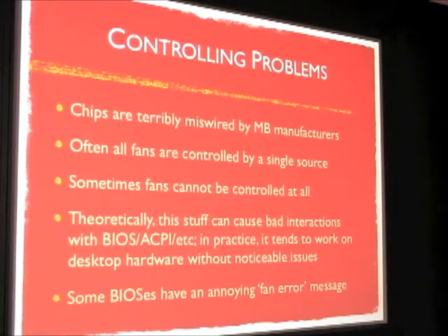And sometimes fans cannot be controlled at all. Sometimes the chip supports fan control, and you can change these registers on the chip, but it's not actually going to affect the speed of the fan, because the motherboard manufacturer hasn't wired the fan controlling pins of the hardware monitoring chip to the actual fan headers of the board.